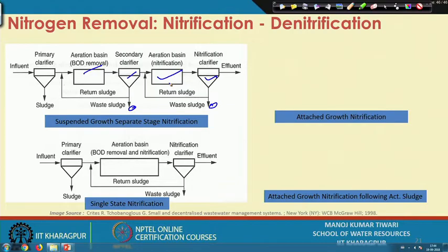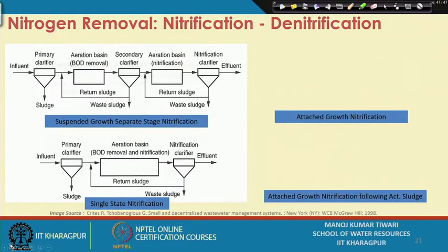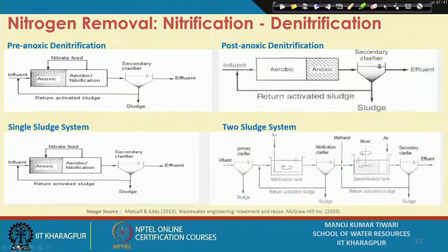We can have single stage nitrification as well. So, we get rid of the other part, and the BOD removal and nitrification are done in a single aeration basin. The only thing is that the residence time has to be a little longer here. There are a couple of pictures which have not come through somehow, but you will get them in the materials when they are uploaded.